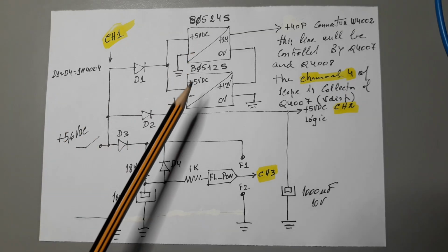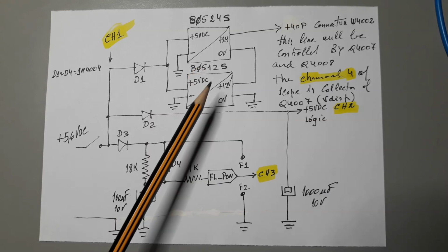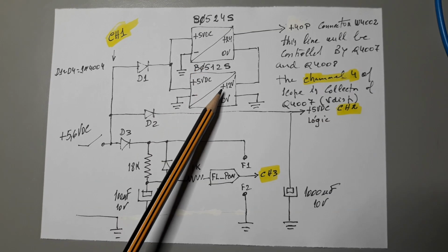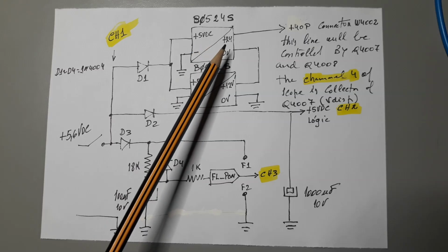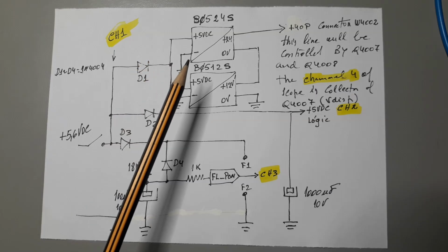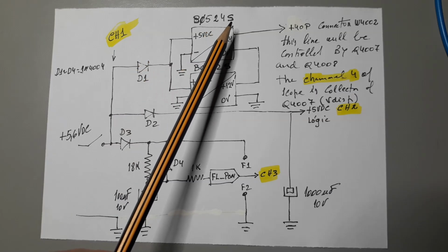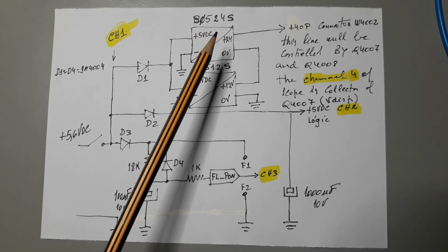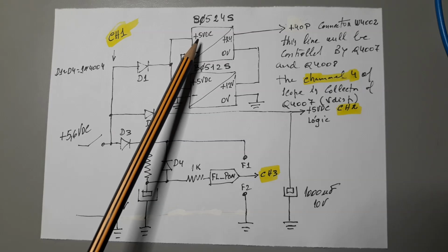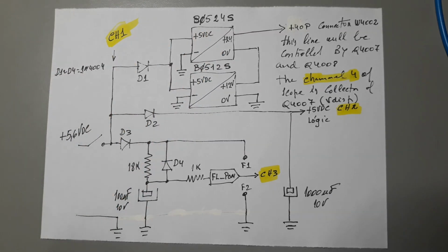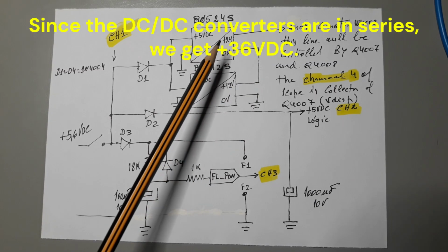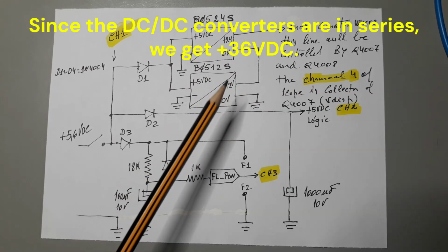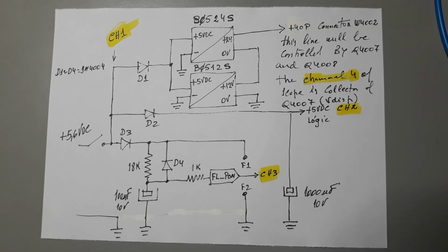And you can see here both DC-DC converters: from 5 volts DC to 12 volts DC, and here the 5 volts DC to the plus 24 volts DC. It's necessary to take into account the letter S at the end. This means the converter is isolated from the input block to the output block. This is very important, okay? Because you can see here I use both converters to create a series power source to the output. The next note is